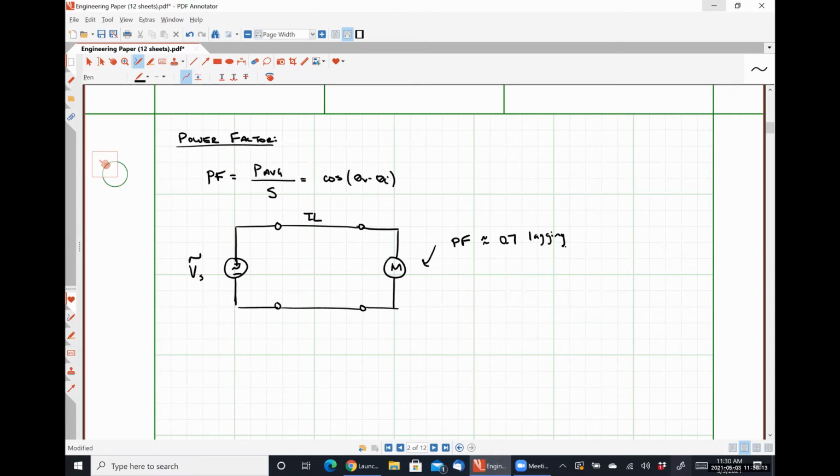There's actually going to be a power factor associated with the transmission line as well, because you guys may not have learned this yet, but you probably will in your physics classes, and if not, you'll definitely learn it in your electromagnetics classes. But a wire in any closed network also exhibits some inductance, okay? So we should expect that our transmission lines portion also operates at a power factor. It's going to be somewhere really close to 1, but it is also going to be lagging because of its inductive nature.